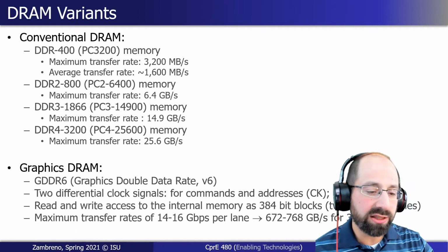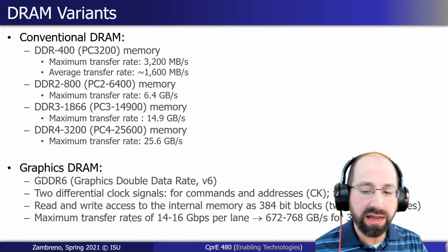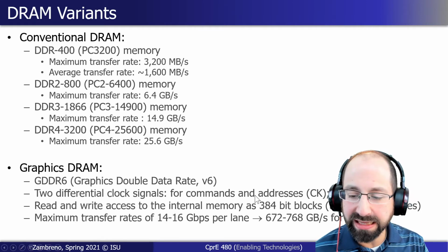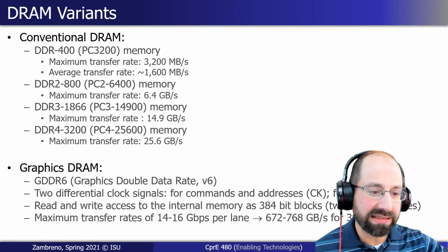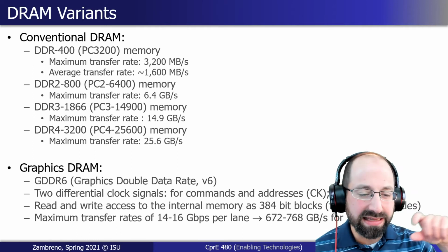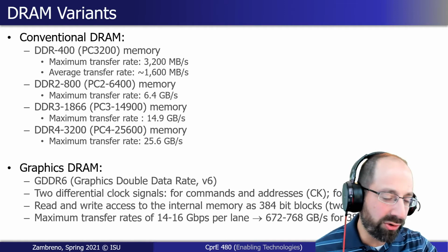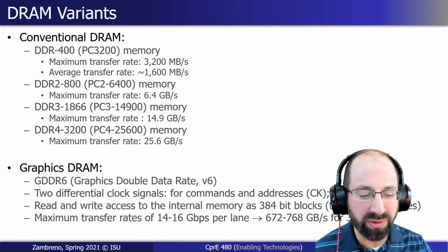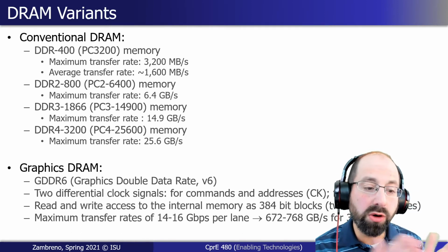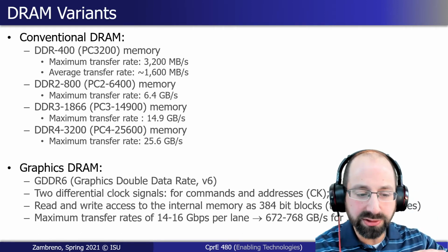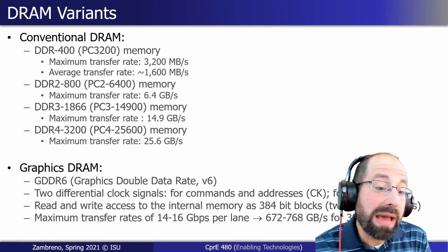To have this particular pre-charge line, it needs to have a value that goes high for 11.2 nanoseconds, and then stays down for 30.6 nanoseconds. And then likewise, this signal, this wire has to be of exactly this impedance in order for this sense amplifier to work properly. All of those very low level VLSI kind of tolerances and specifications are what go into something like a DDR or DDR2 or so forth spec. There's nothing magical about it.